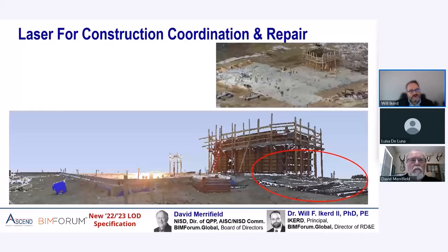And that's an important point because technically speaking, those anchor rods could not be modeled to LOD 400 fabrication level with just laser scan data. And the reason for that is the laser scanning can't see through the concrete. As we look at other examples of this, the key points here are AISC tolerances. Additionally, if teams are specifying things like anchor rod scans, it's frequent to have pockets that the anchor rods are in on projects. And one of the things you have to always think about there is debris.